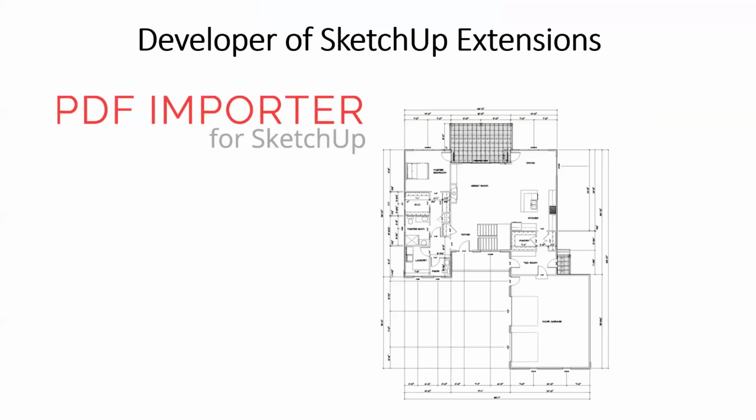As builders, we typically get PDF drawings of floor plans, elevations, and that sort of thing. You can import a CAD file into SketchUp Pro, but you will not get the text and everything you see in this image here. When you're trying to make a model on top of something like that, it's really helpful to be able to see the text, to know what size door or window it is or what a dimension is. So PDF Importer will allow you to directly import a vector PDF into SketchUp.